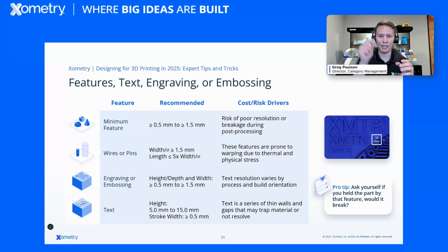Sometimes I call a pin in the wrong place on a 3D print design that's otherwise perfect a god pin because if it breaks, your entire part is scrapped. That's where I ask, maybe you should make that into a sacrificial feature or use a metal pin and make a hole there, something to take that vulnerability away in your design.